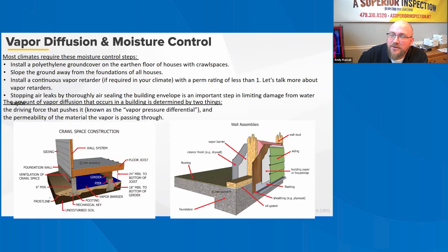Materials that significantly slow down the vapor diffusion process are said to have a low permeability, or simply low perm, and typical building codes can consider a material to be a vapor retarder if it has a perm rating of 1 or less.